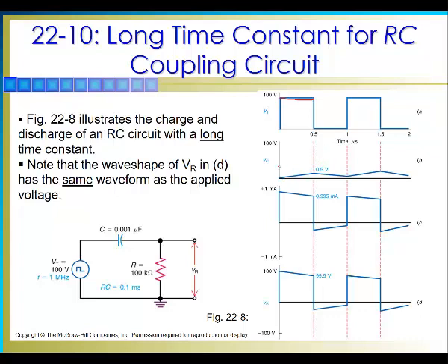But the time constant here seems to be very large, because on the first duty cycle of the voltage, the capacitor only gets 0.5 volt charge, and then the voltage turns off, it starts discharging and then charging again. But as you can see, it never gets even close to the 63%.